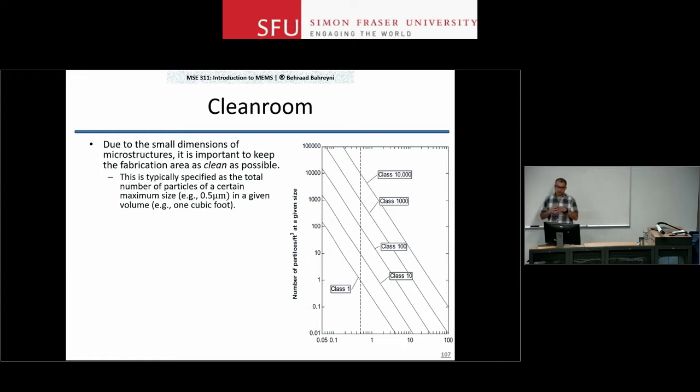If this happens during the processing, we are going to see that it can actually mask the information that was on your mask. Right? So you can basically get another layer of image protection from this particle that wasn't intended and that can ruin your device. Basically, the device is made in the wrong way. In case of MEMS devices, a single particle can actually disable the device.